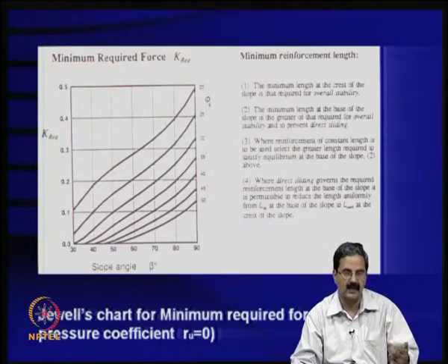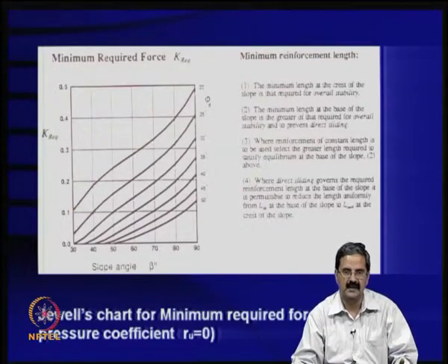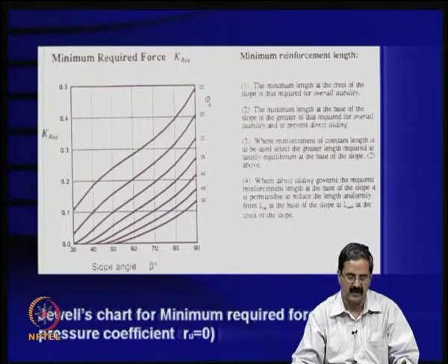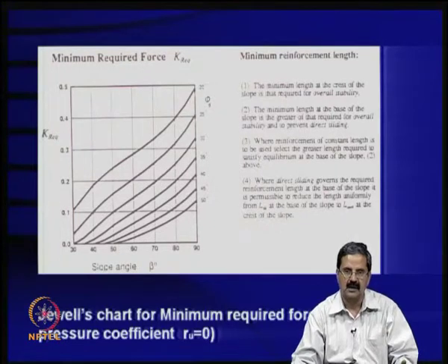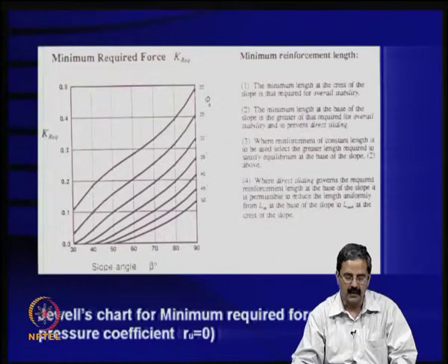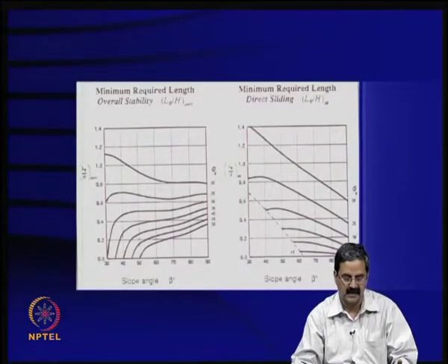resistance to really see that it can sustain some horizontal force, either in the form of lateral pressure from its own weight, or because of the earthquake, or because of the seepage forces and all that. So, of course, there are many design charts developed along these lines, but I find that the Jewell charts are much more elegant to use and simple to understand.